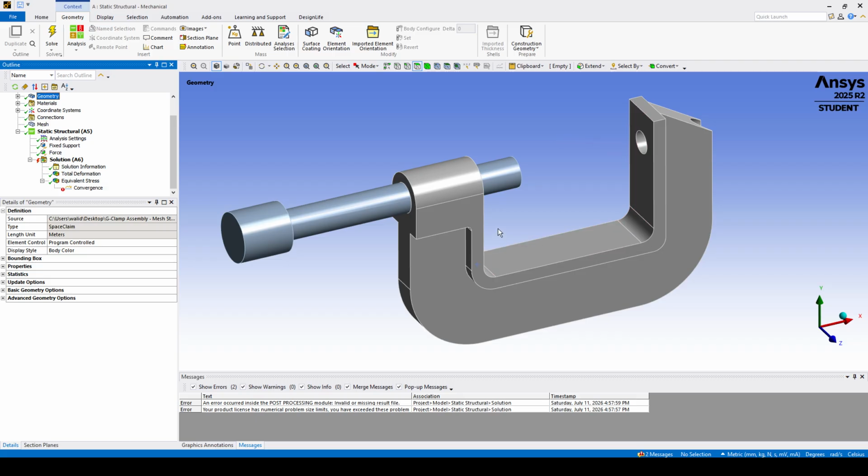Even when your model is complex and you don't know where the highest stresses are, you can do a first calculation, and based on that you can adjust or enhance the second simulation. So understanding where stresses occur, recognizing stress gradients, and choosing the appropriate refinement techniques are skills that separate experienced simulation engineers from beginners.